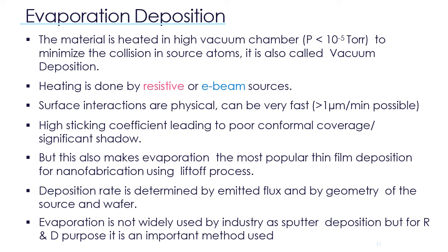So high sticking coefficient leads to poor conformal coverage due to significant shadow. But this also makes evaporation the most popular thin film deposition for nanofabrication, which uses the lift-off process. The deposition rate is determined by the emitted flux and by the geometry of the source and the wafer. This kind of evaporation is not as widely used in industry as sputter deposition, but it is used for R&D purposes, so it's a very important method.